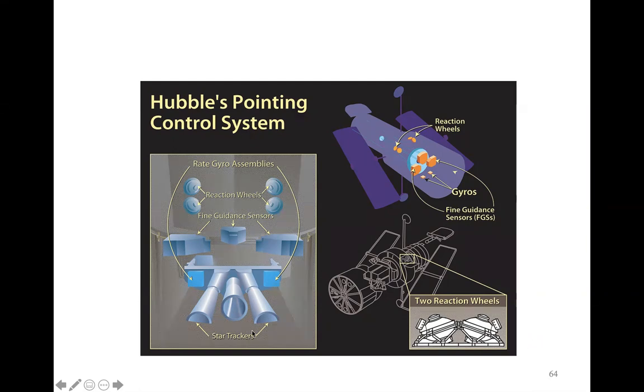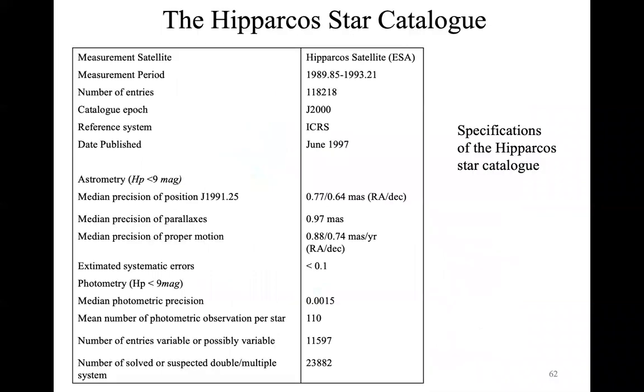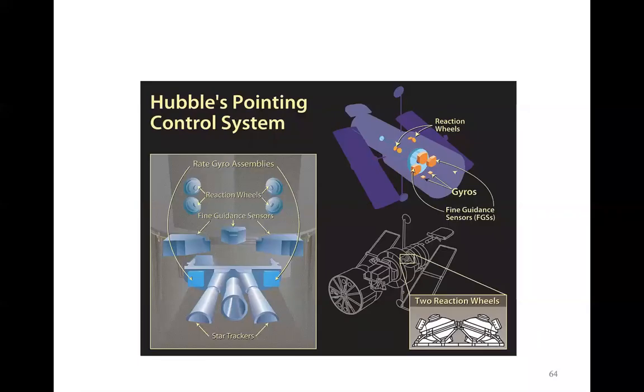And during my lecture, I said that if you want to determine the attitude of a spacecraft, you want to have, for example, two star trackers that point at two different regions of the sky, because you want to determine the attitude in the triaxial reference frame. So you want the correct determination of the attitude, for example, of a three-dimensional stabilized spacecraft.